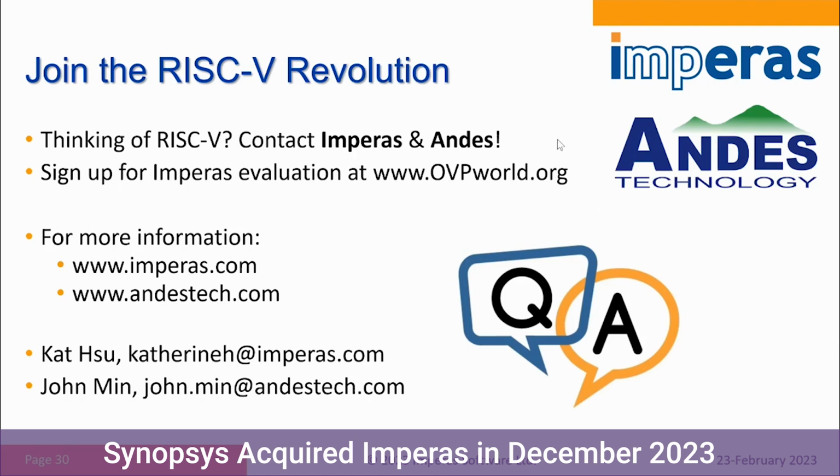Okay, there's another question from an anonymous attendee. Can you share information if there's a matrix instruction extension on the way? There are two ways. RISC-V is always evolving, so there are always instructions being proposed and the community is debating. A bitwise operation extension was recently approved. A vector instruction set has been approved. A DSP instruction set is going through approval. And additionally, you can create custom matrix instructions.